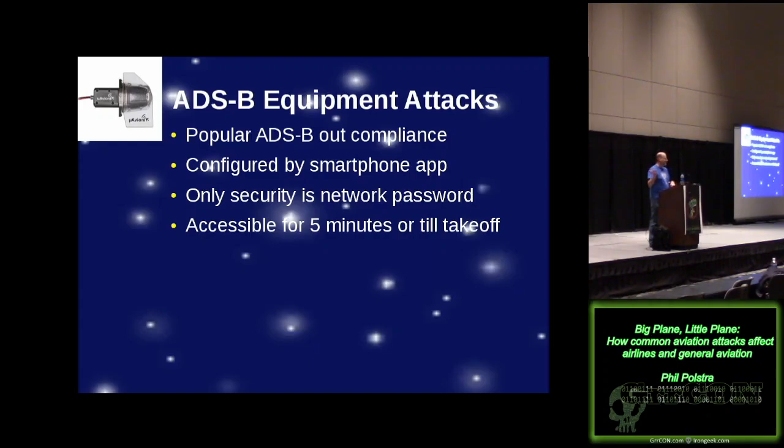Here's what their company does. They make these little units where you take off one of your navigation or position lights, normally on your wingtip, and put their special light in its place. That special light has a high precision GPS receiver so it can send out your position, an ADS-B transmitter, an altitude sensor, and some other smarts.